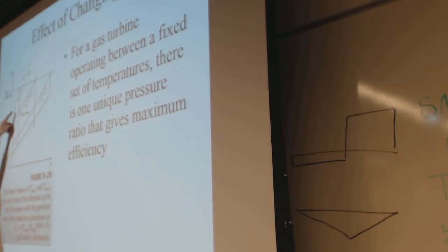So this is saying we got a pressure ratio of 15. What's that mean? We had to add constant entropy. The temperature correlates with pressure, so it went up to a high temperature. We added a little bit of fuel, and then it came down. And this is how much heat is missing in the cycle, how much work got done.